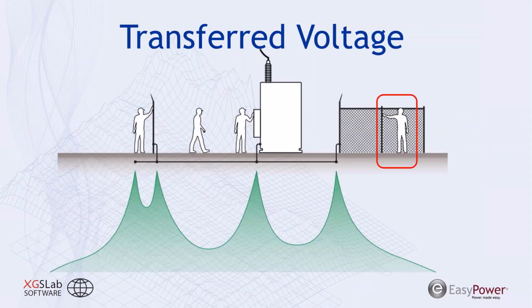An illustration of this would be on the inside of our substation, where you can see the supports for the barbed wire for our substation fence. This would be a typical touch voltage analysis. We look at a step voltage analysis and a touch voltage, but for this individual touching this fence that may be directly run to this substation fence, this can be considered a transferred voltage.